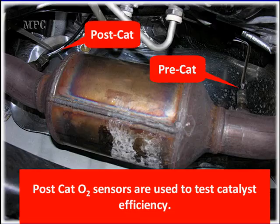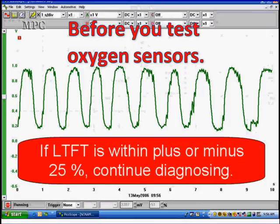This particular vehicle we looked at here has three O2 sensors. One right by the manifold, which is a pre-cat, one right before the catalyst, which is pre-cat, and one after the catalyst. We do this for catalyst efficiency testing, and we're going to show you an absolutely valid catalyst efficiency test. But before we do any of these things, before you test anything, you must make sure we have normal